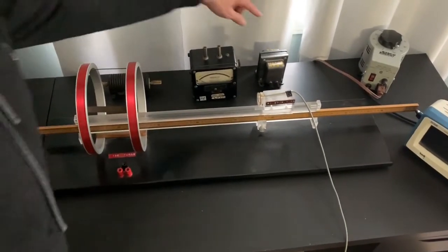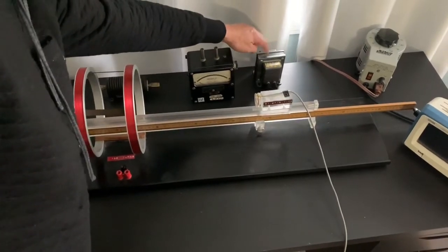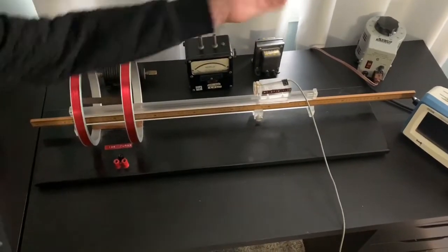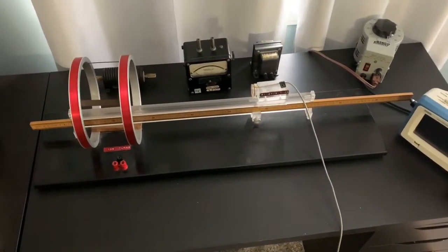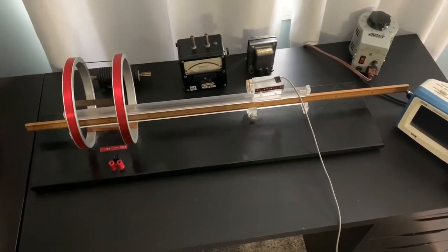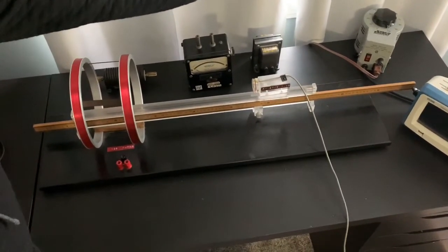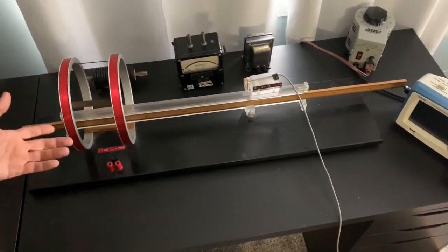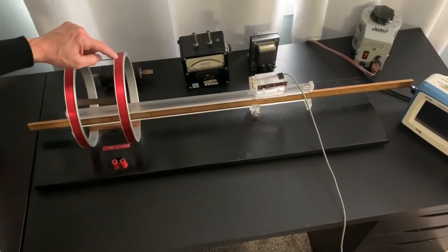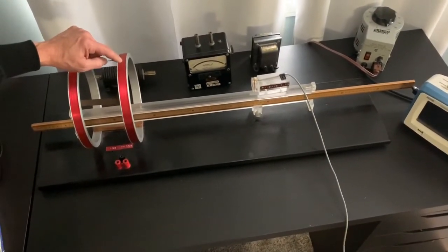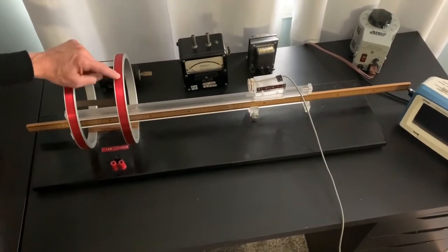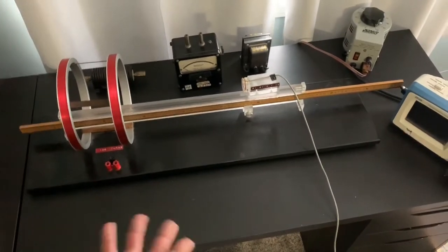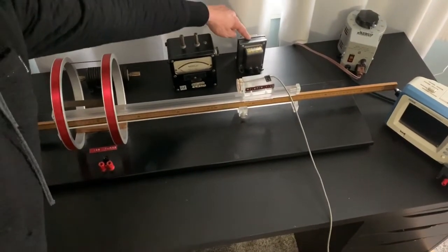Logical question, however, now that I think about it, is why even use this guy, right? Why even kick down the 120 volts to 6.3 if we have that there? And the reason being, well, it's all about safety. You could inadvertently have that pretty high up on its scale, and you'll be working with a current that's close to 120 volts, and you can get hurt. Not only that, but the current from a voltage source that high is going to be incredibly high. So the current in these wires will generate a lot of heat, insulation could melt, equipment fails. So this is like a safety device.